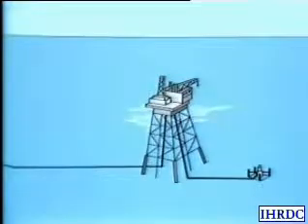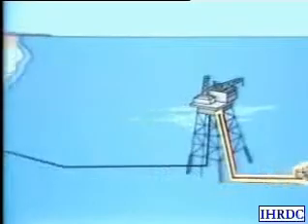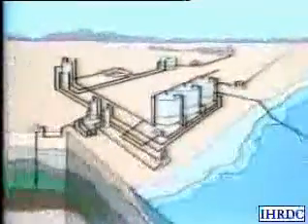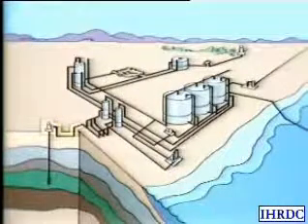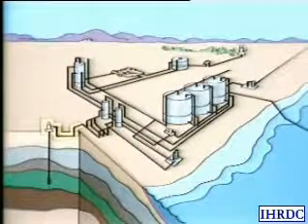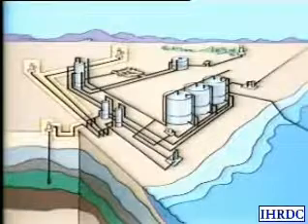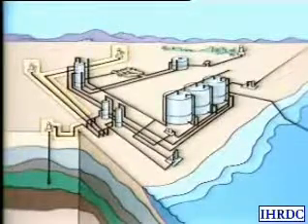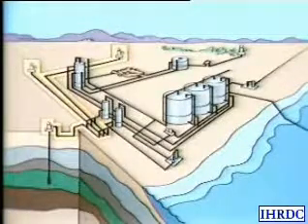The produced fluids leave the Christmas tree and enter a surface flow line system, usually a 2 or 3 inch pipe, which may be on the sea floor for subsea completions or below or above ground at onshore installations. If the production facilities are shared by a group of wells, as is often the case, the flow line will probably connect to a header or production manifold.